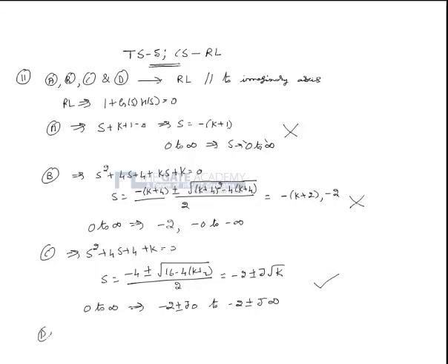So just to verify, as per the option D, the characteristic equation is s square plus 2s times (k plus 2) plus 2k plus 1 is equal to 0. On simplifying, we see that the poles may be real and or imaginary. So we can't comment on the root locus being parallel to imaginary axis, as it is not the case. So the option D is not the correct option.